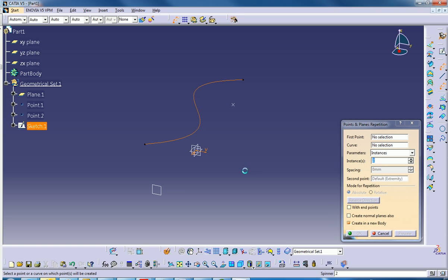Well, I'd like this curve to be selected. How many would you like to be on it? So I can say I'd like 8 points built. I can preview that, and you'll see that the software can drop these 8 points for me. If I find that's too high, I can drop it down to 6. Preview again, it will space it out evenly.